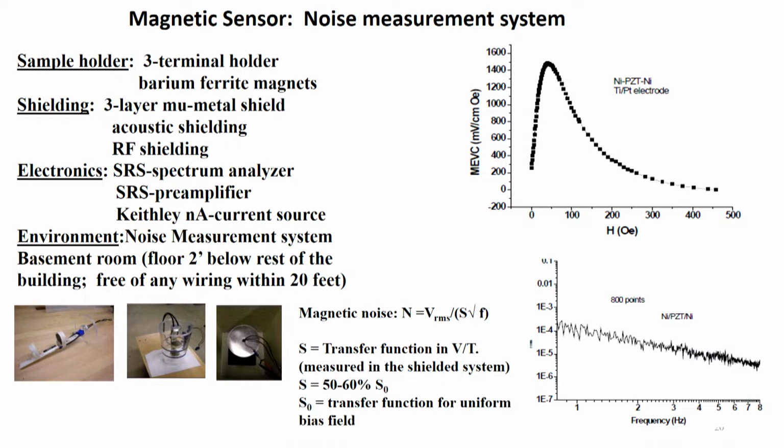So, how do you find the lowest field it can measure? The only way to do that is, do not apply an AC magnetic field, just measure any signal that is present across the PZT in the sensor element and feed that into the spectrum analyzer.